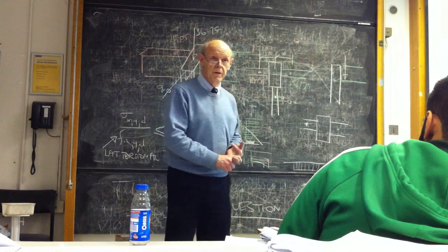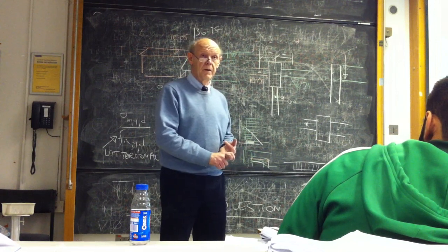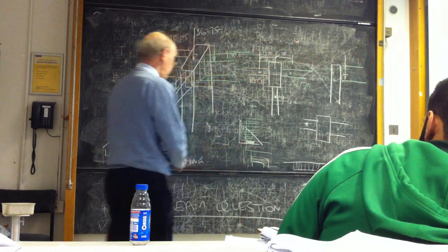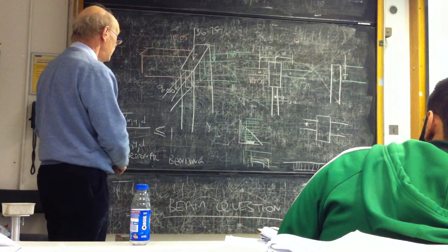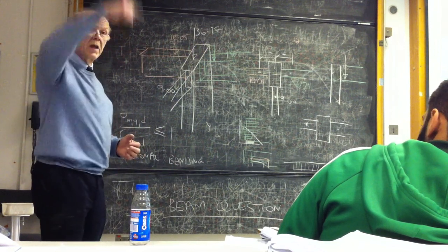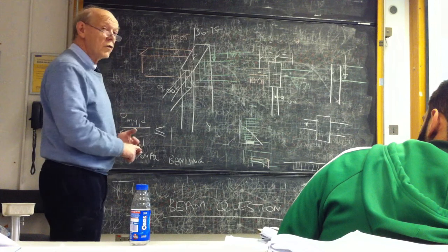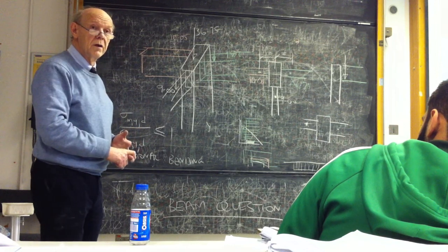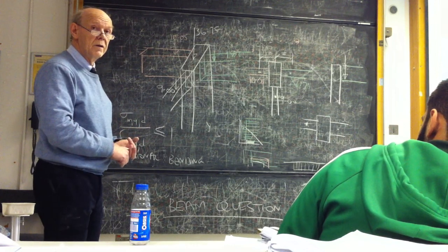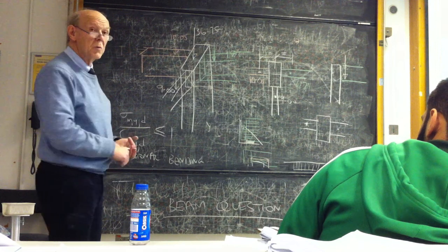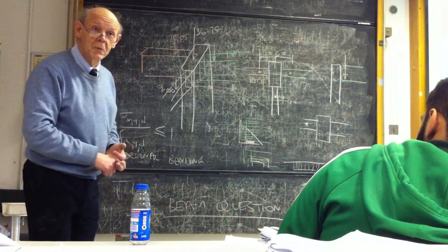So even if it was restrained like halfway along, you still only look at the z-axis? You mean you're talking about restraint in the height? Yeah, no, you look at both. But there's only bending about the z though, isn't there? Yeah, but it still might buckle about the y, even though it's not being bent about the y.